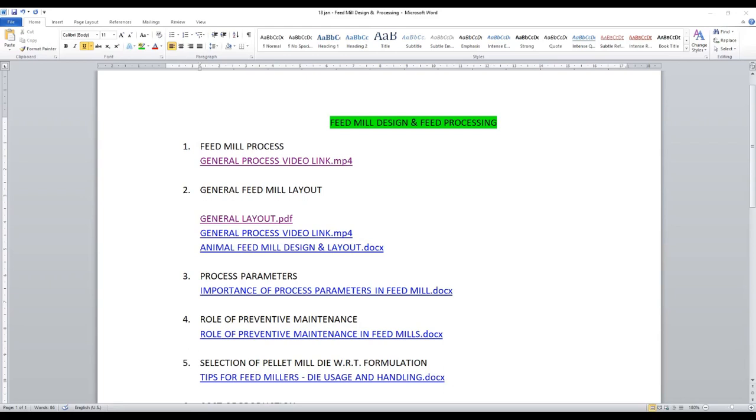Even in Haryana, with the help of stackers, feed millers are utilizing stacking heights up to 30 feet, getting the maximum efficiency from their warehouse storage. So generally, we multiply the raw material requirement by a factor of 6. That will be the total square feet of the warehouse.